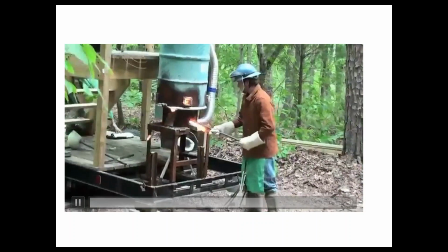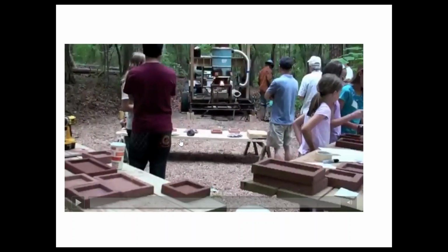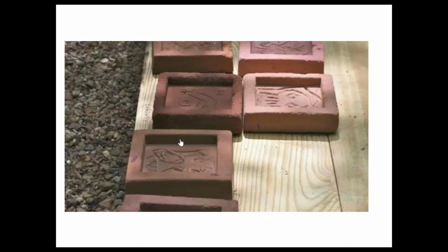This is a small cupola, and basically when you're melting the steel that way, you're allowing the carbon in the charcoal to react with the iron oxide and the ore and form carbon monoxide, and that creates a lot of heat, and it also allows some of the carbon to go into the iron, and that high carbon iron has a lower melting temperature, and the reaction of the oxygen with the carbon raises the temperature so that you can actually make cast iron.